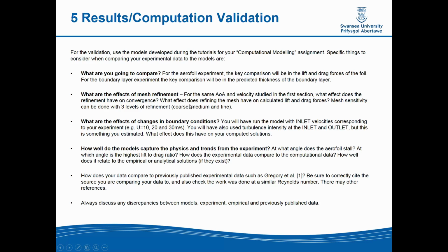With the results, a little bit of this is, obviously you need to put in the different velocities that you used in the experiment. You need to match your flow conditions in the experiment as close as possible. So by using the same density for that atmospheric condition, that gives you a good link into the right air properties. The validation, how are you going to do that?